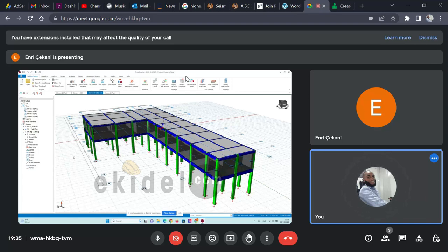That bar is called a bi-diagonal reinforcement, and it is found one in a beam, two in a squat wall, and three around the coupling beams in a wall. So this is where you can introduce this bi-diagonal reinforcement.